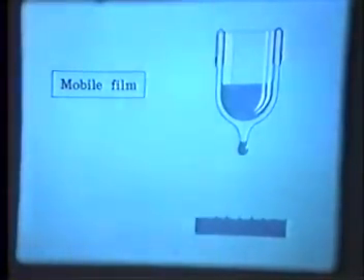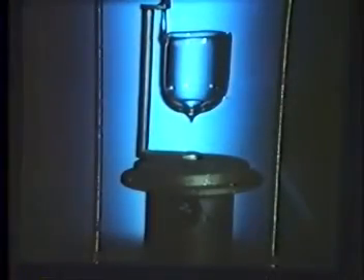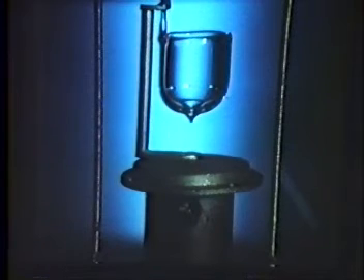To show this, we are going to use a small beaker like the one sketched. Film is pulled down the outside by gravity and replenished from inside, and it drips off the bottom at a constant rate until the beaker is empty. The actual beaker, 17 millimeters diameter and about the same height. The copper rod underneath dips into the bath and helps to keep everything at bath temperature.